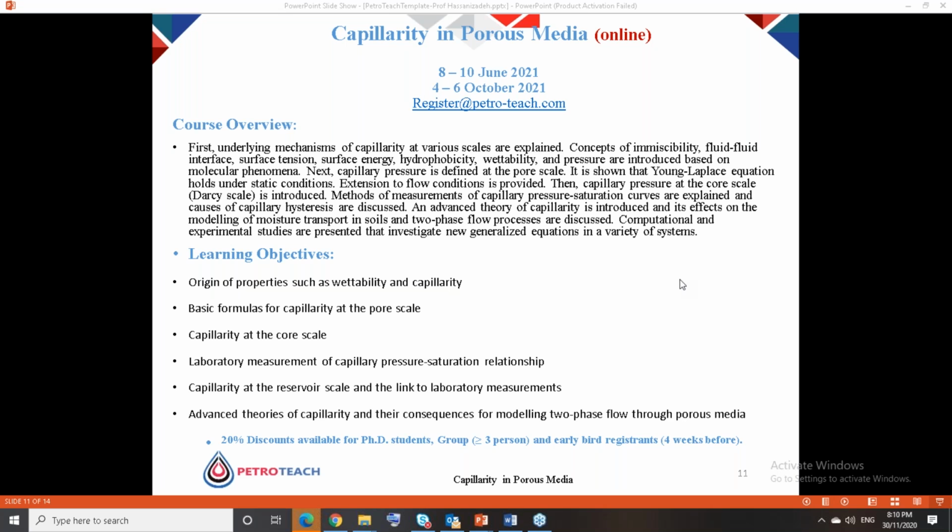you can see that the pressure gradient you have in phases will be such that the pressure difference between the two phases could be much larger than capillary pressure, because the capillary pressure really is the one that you have at the meniscus, and that is never zero. It just could be negligible compared to the pressure difference between the two phases when there are large viscous forces active. And yeah, there was no time for me to go through that, but I can show that.